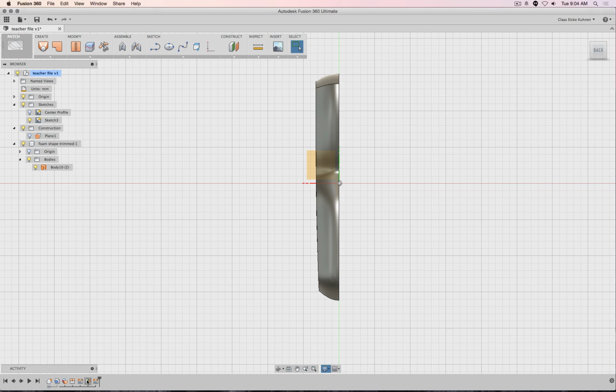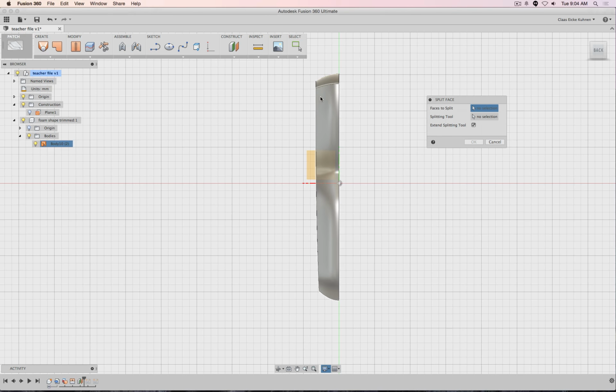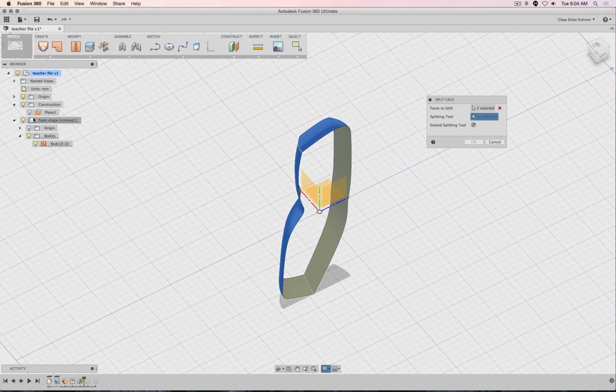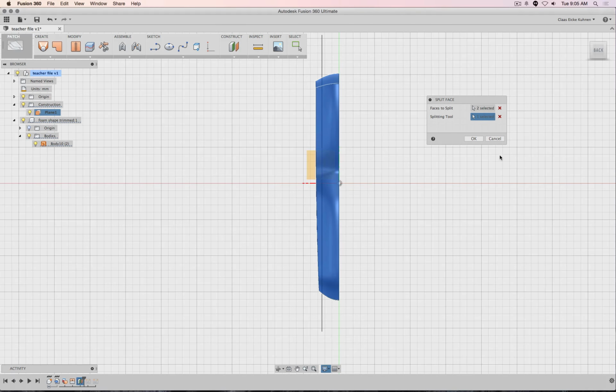So with this plane which I created, I'm going to push this one back to here at the beginning, simply because then I'm trying to restructure my design a little bit. I'm going to split actually those faces along this offset construction plane. There you can see actually how and where it's going to split it, and it's a plane or planar. So yeah, split. Perfect. Okay.